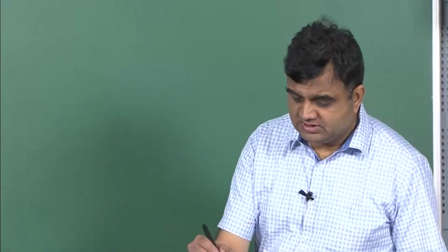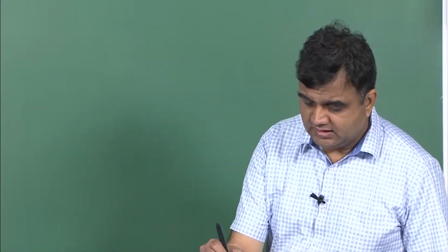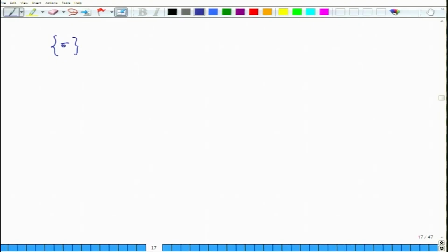So, what we have shown is that we can now calculate sigma x, sigma y, tau xy, when you measure stress with respect to the x and y plane. That is equal to a matrix Q bar times a strain vector measured with respect to the x axis, and we know how to calculate all the elements of the Q bar matrix.